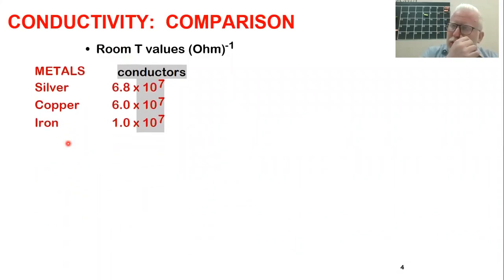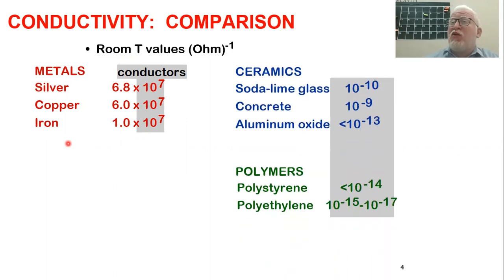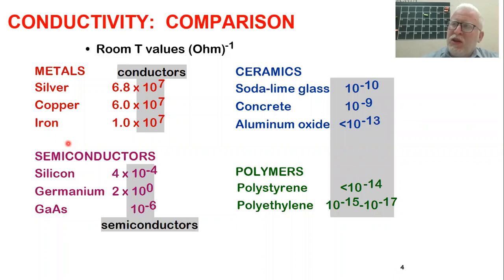The first set has a relatively high conductivity sigma, in the range of 10 to the power 3, 4, 5, 7, 8, something like that. Another set has an extremely low sigma, 10 to the power -15, -14, something like that. And you have a family in between, not that high like the first one, and not that low like the second. Accordingly, you can classify your materials based on the conductivity.